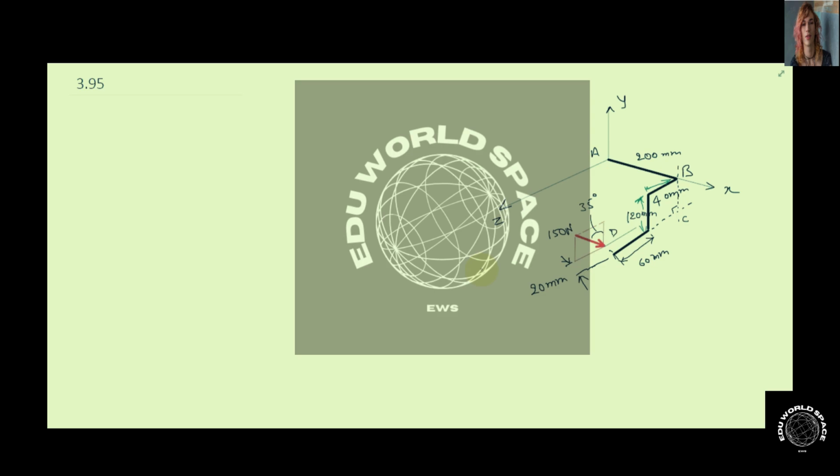Problem 3.95. In this problem, we have to calculate the equivalent force couple system at point A, that is the origin of this system. For the calculation of the equivalent force, since there is only one force acting on the system, the force itself will be the equivalent force about point A.